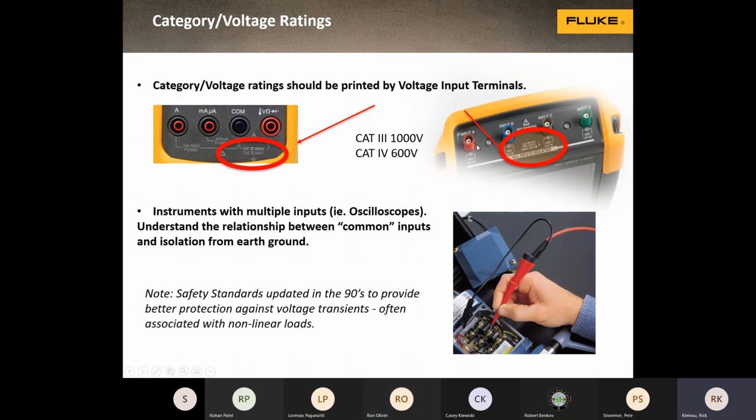But these are plastic, and these things run on batteries too, the scope meters. On the Fluke scope meter, the 120 series scope meters and the older 90 series, they are isolated from ground, but the reference inputs are common.